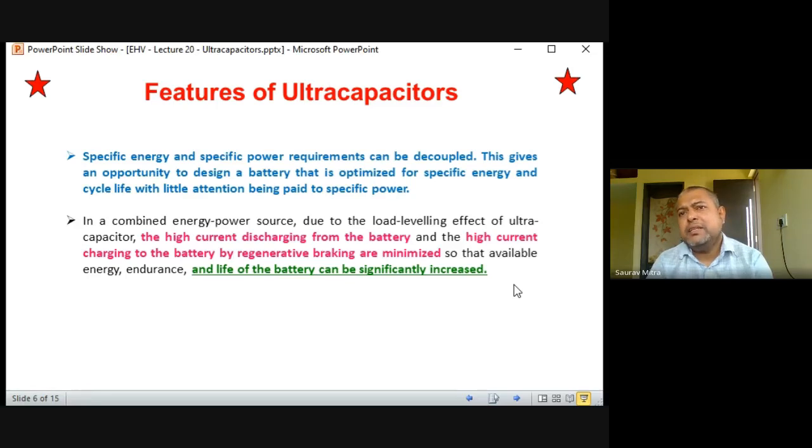Okay, so one discussion is there. What is the main requirement of a vehicle power source? Its specific energy should be very high. That is the only requirement. If the vehicle is running on flat land, a high specific energy source is no problem. It alone can handle the vehicle. But if the vehicle is expected to start at minus 25 degrees centigrade, or is supposed to climb a hill, you are actually doing stress testing on the battery, to see how well it behaves in very demanding situations. In those cases, only a battery is not possible.